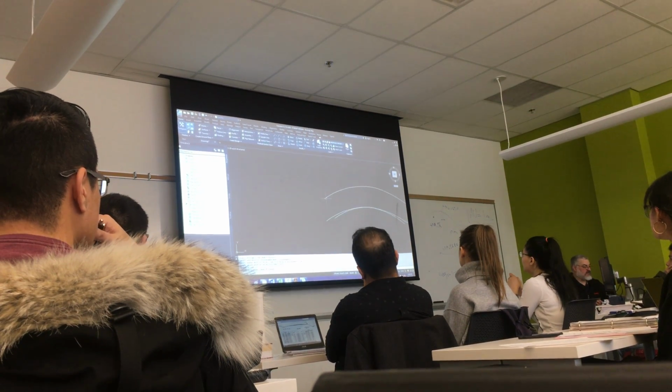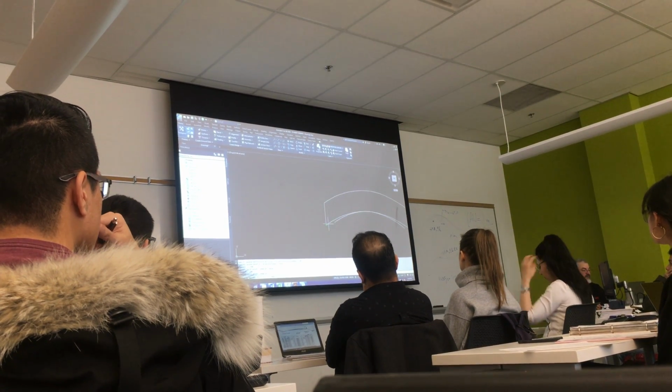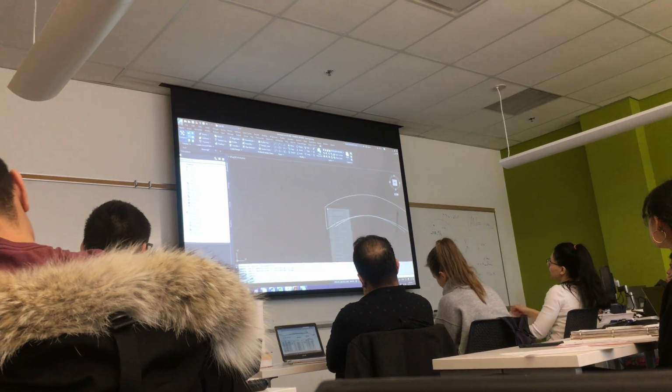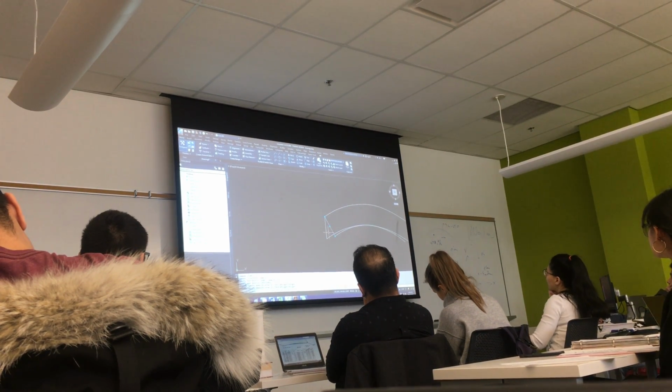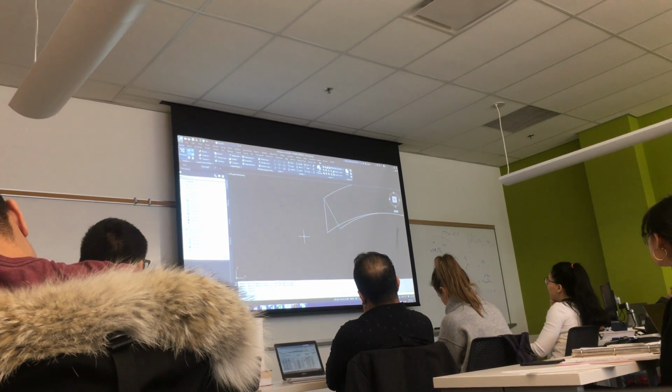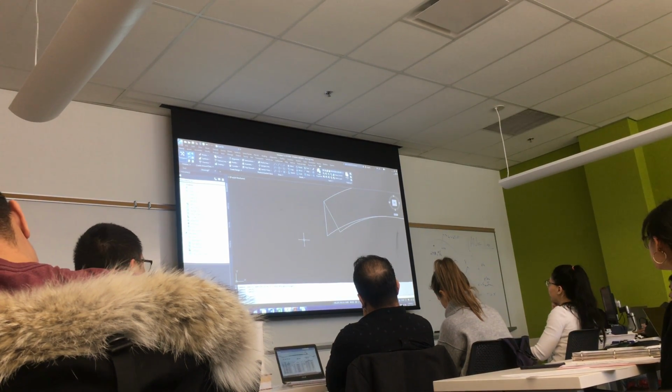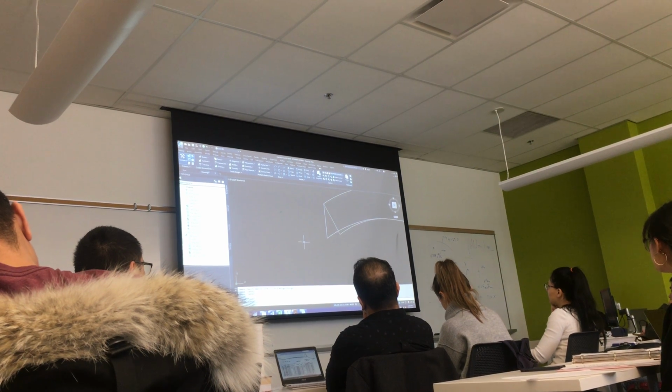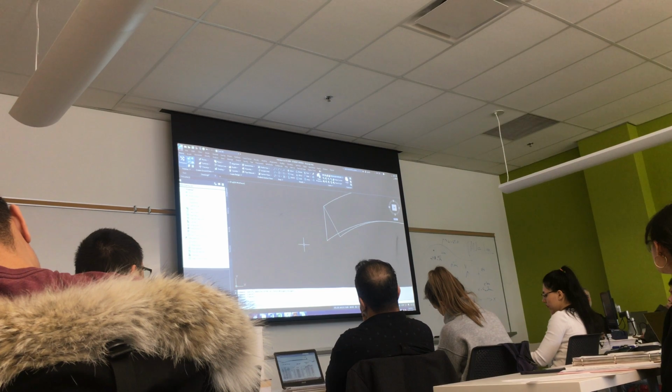This is what I mean when I say thickness. So on a vertical curve, that's what I mean, not this. Both of these dimensions are 10. This one is not how we do it. Okay? So you want to work in this industry, when you talk about thickness of material or depth of material, it's always vertical. Plumb, straight down. Okay? It's a hard habit to break if you're not used to it.